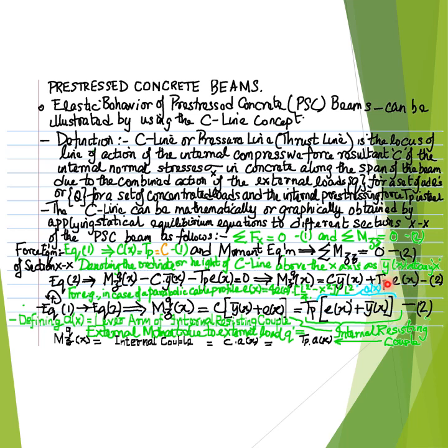An example of a variable eccentricity function, that is an eccentricity function depicted as E with the argument x, thus signifying that the eccentricity of the pre-stressing cable below the centroidal axis of the pre-stressed concrete beam is a function of x.